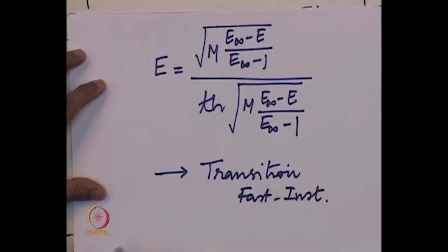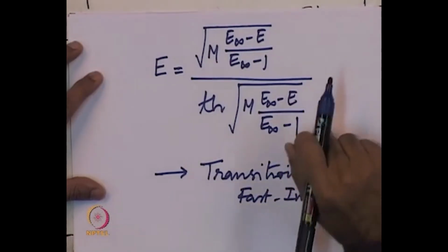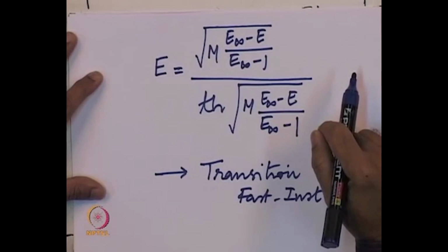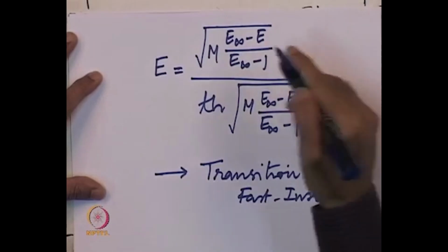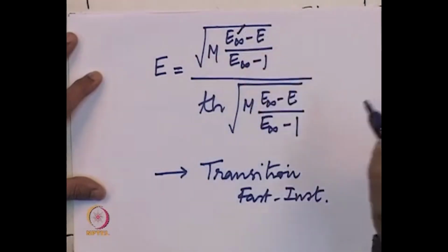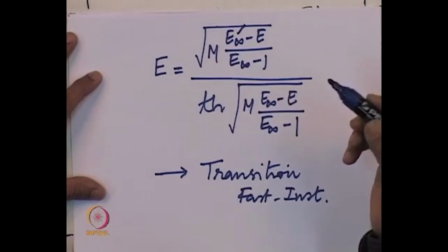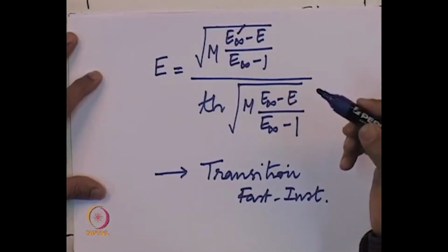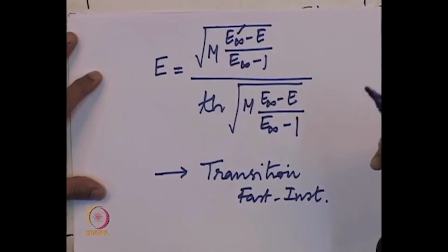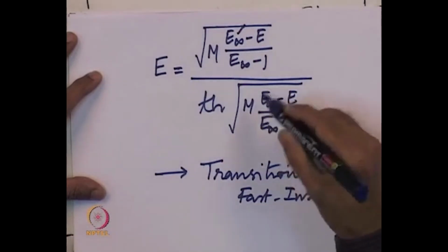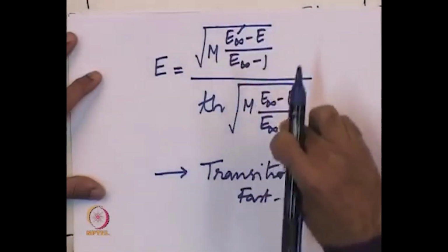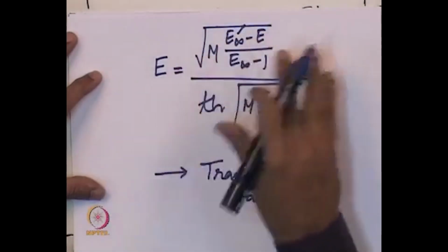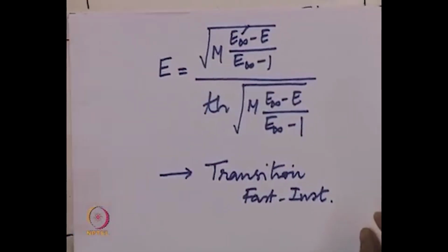So, the only difference between the way you calculate enhancement factor in the surface renewal theory and the way you do it in film theory is that while you are using the same expression, the value of E infinity that you use comes from the penetration theory or the surface renewal theory expression, which is different, as we have seen, when the diffusivities are different as compared to the film theory situation. So, the definition of E infinity is what changes in this expression depending on what theory you use.